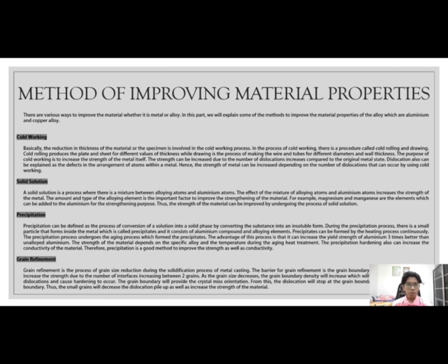The purpose of cold working is to increase the strength of the metal itself. The strength can be increased due to the number of dislocations increasing compared to the original metal state. Dislocation can also be explained as defects in the arrangement of atoms within a metal. Hence, the strength of metal can be increased depending on the number of dislocations that can occur by using cold working.